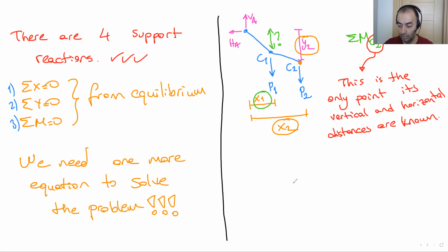We cut the system. We write these total MC2. By the way, when we cut the system at point C2, at the right-hand side of the point C2, there was a cable here. We cut the system from there. We have to consider its effect here because it has a tension. You know, cable carries the tension. It acts at this point. So we have to draw the tension load here.